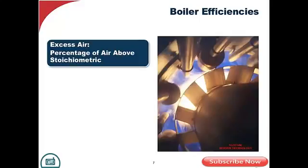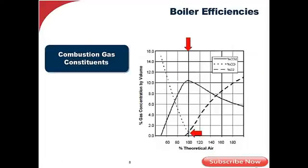So what is excess air? Well, it's nothing more than that percentage of air which is above the stoichiometric, 100% combustion efficiency. Remember, when we talk about combustion efficiency, we are only talking about the effectiveness of that burner to properly oxidize the fuel, the air, and combust. So when we talk about excess air, it's that percent of air, that volume of air, which is over stoichiometric combustion. Let me show you a curve.